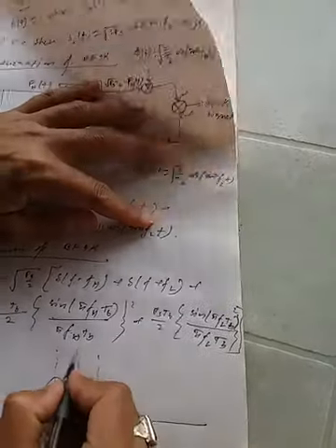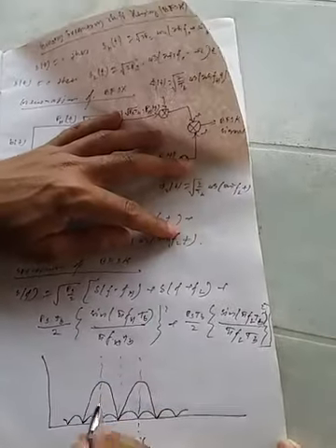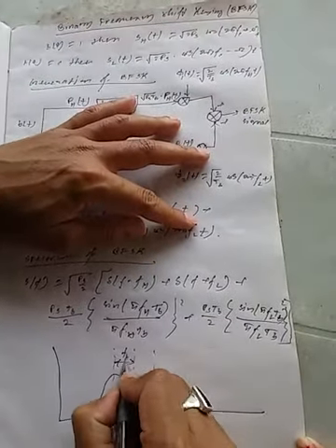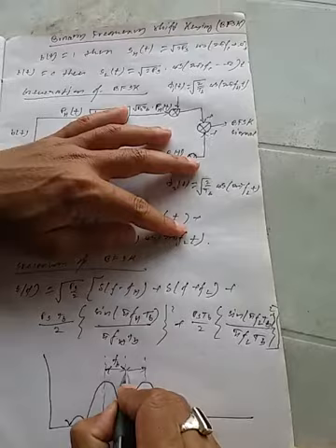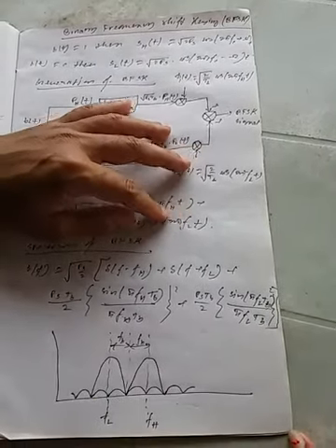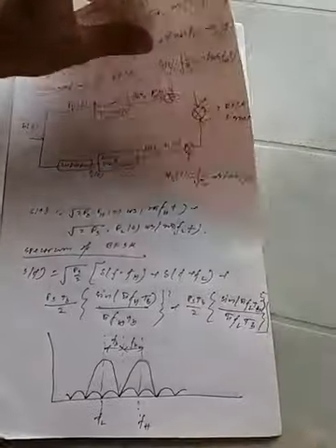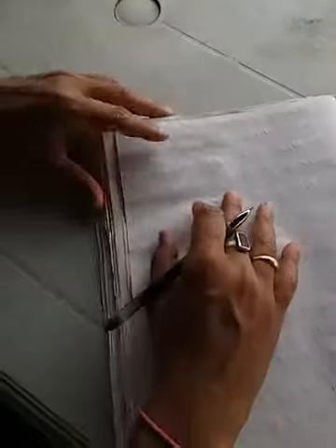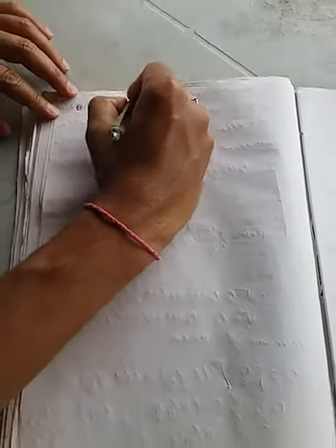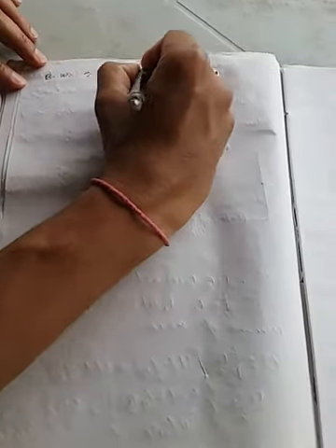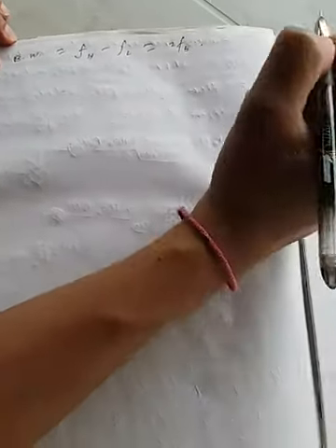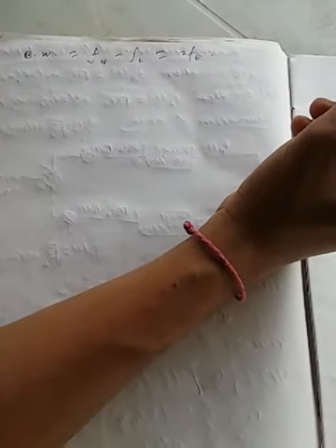And this is the frequency for transmitting 1 bit, so this is fb, right? So this is also fb. So what will be the bandwidth? Bandwidth will be equal to fH minus fL, right? That will be equal to 2 fb. So this will be the bandwidth part.